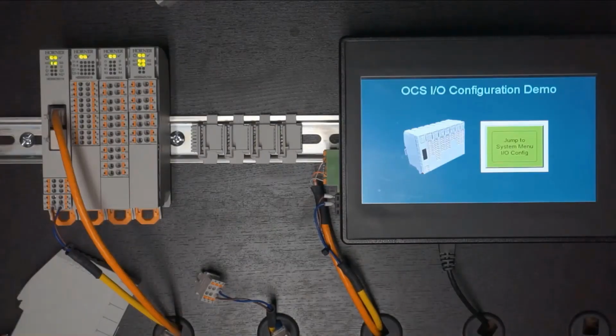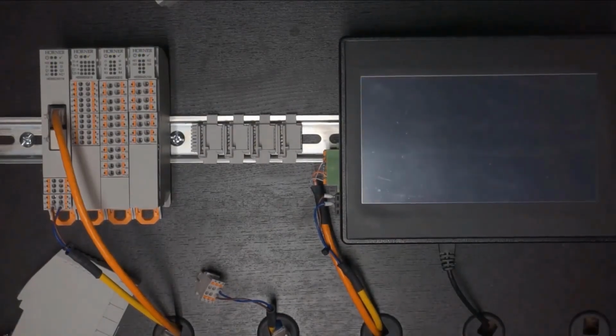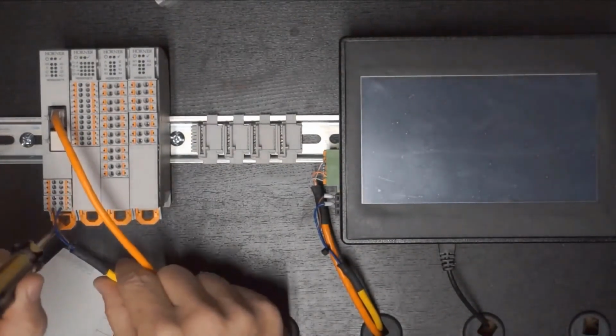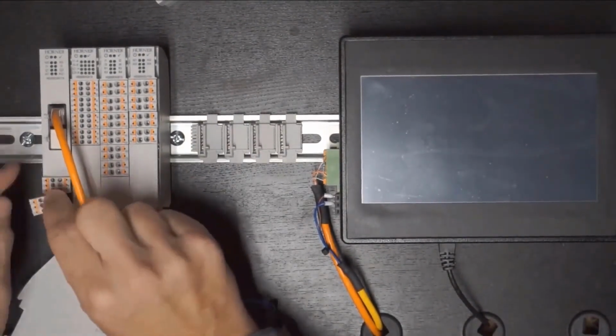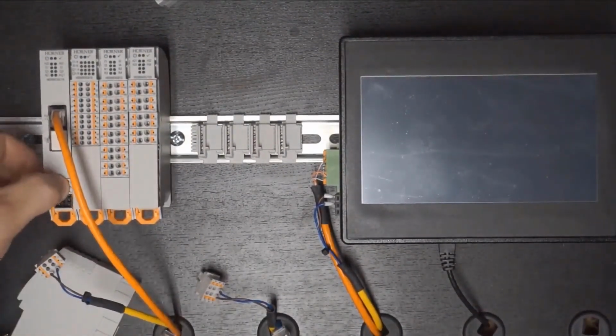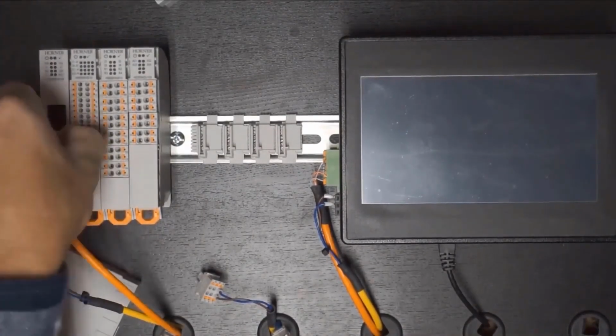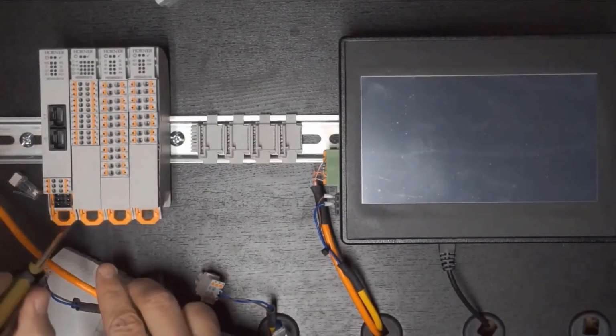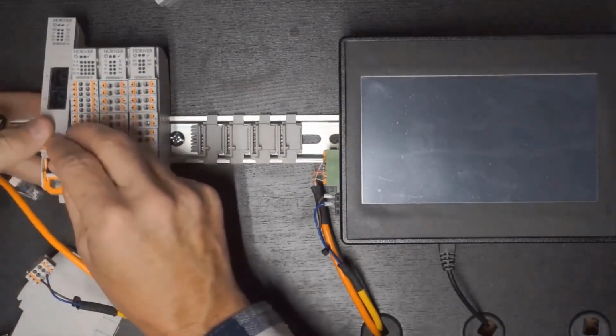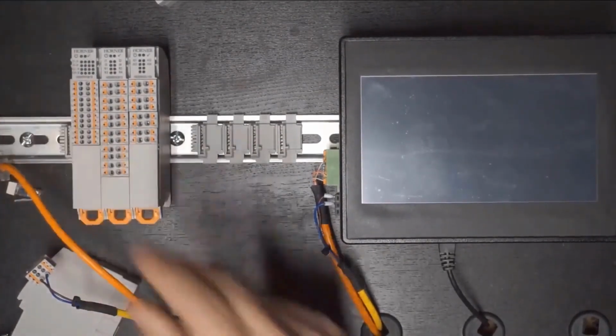For the next demonstration, we'll see how you can swap out a CNX base in the field without opening Cscape. So firstly, we'll power the system down. Then we'll pop the power connector from the existing base, disconnect the communication cables and save the terminating resistor. Then we'll remove the existing base, and we'll add a new base.